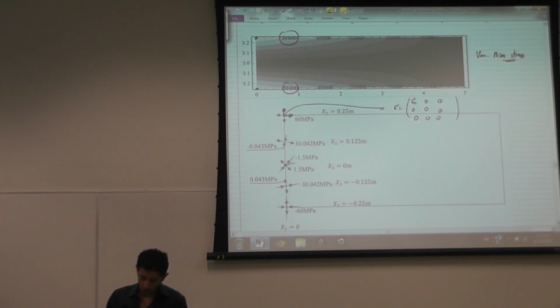The stress matrix at this point, sigma 1 is 0, but I have shear stress. The only stress I have is shear stress. And so the eigenvectors are aligned at 45 degrees. And in between, the eigenvectors are according to the interaction between sigma 1 and sigma 2. So in the middle, aligned at 45 degrees. At the top, they're aligned with our basis vectors.